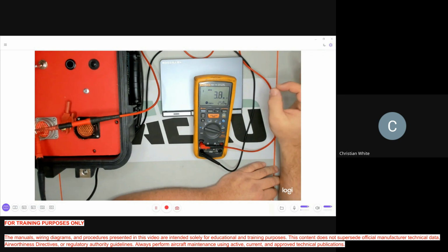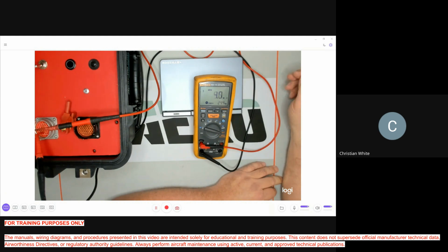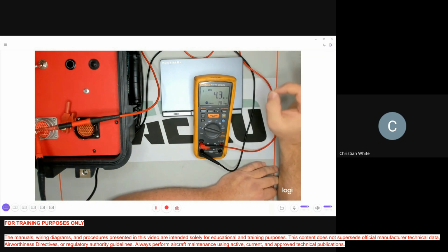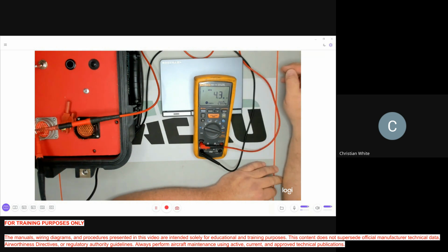So what it is, the voltage that I have, and it's actually shorting out. It's saying it's shorting out at about 200 and some volts DC, but at 500 volts, it did not jump that gap that I have in here. It took it to 1,000 volts. So you can't say, oh yeah, I tested at 500, it's good to go.